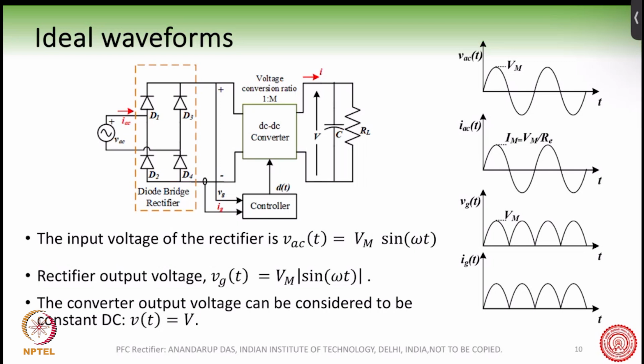I will come to this a little later, but the buck converter or a buck-boost converter has a discontinuous input current taken from the source, and that creates more challenges when we want to ensure power factor correction operation. So the boost converter is an ideal choice, right?